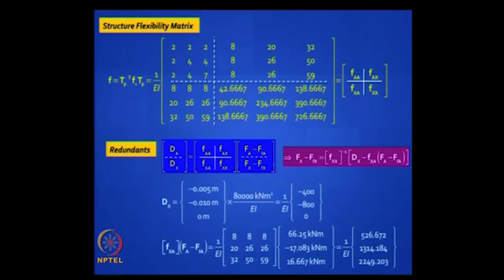You get F and just check that it is symmetric, because the lower right hand corner holds a secret. Make it as precise as possible. That is why I put 4 decimal places there, I put 6 significant figures, because that is the fellow you need to invert. If you round off heavily there, the inverted matrix will give you some answers, but when you multiply it with this matrix, you will not get an identity matrix unless the accuracy is high.